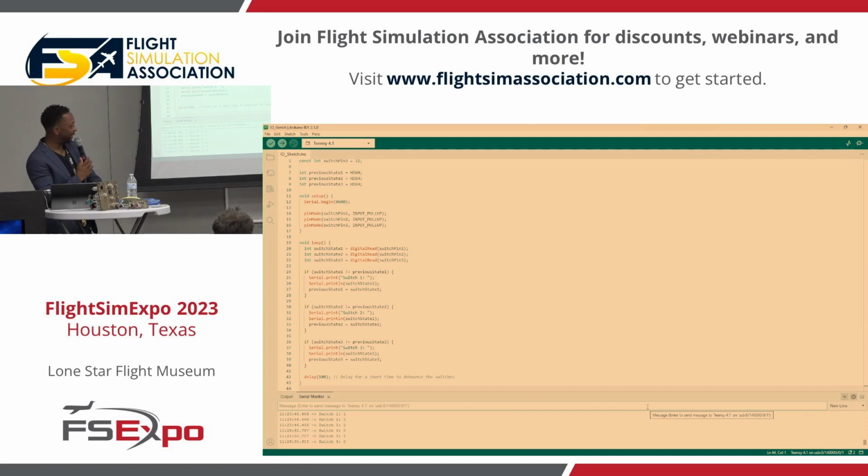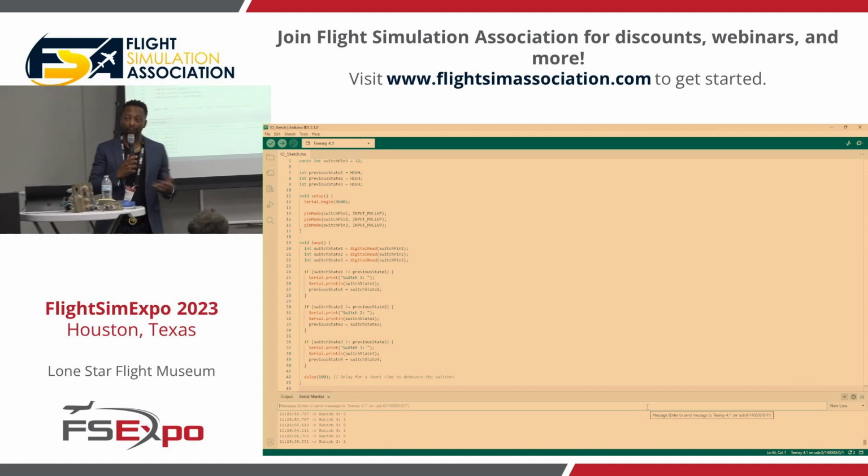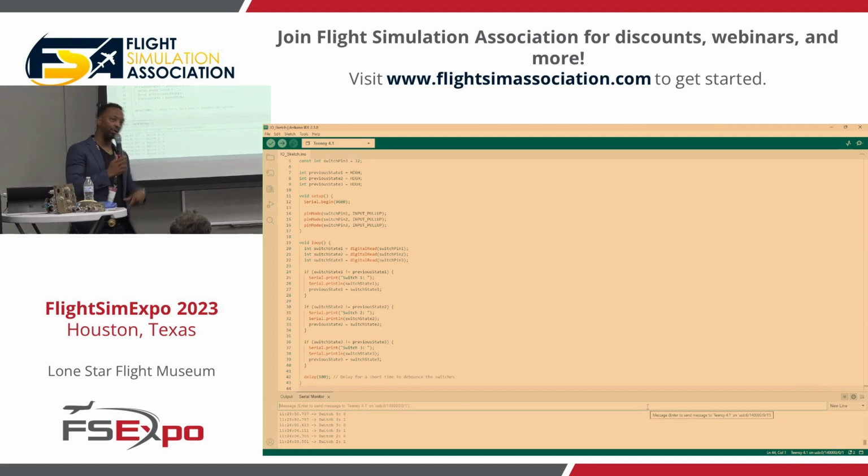But if I come and push a button, there's switch 3 that went from high to low. And now it went back high because I let it go. Same thing with switch 2. And you see as I'm pushing the buttons, they're going to 0. Remember, Arduino can either be pulled down or pulled up. So this tells me that I'm pulling the switches down to 0.